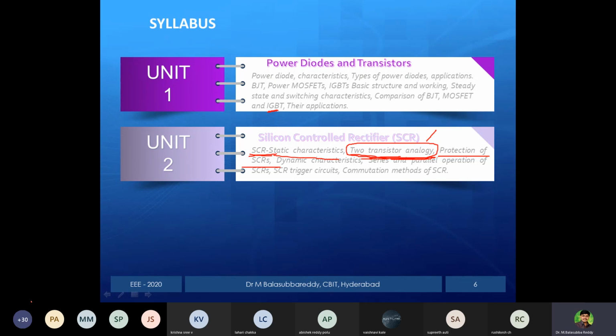This loss is converted into heat, and that heat is generated in the armature. If you do not cool it down and continuously run the machine at full load, the losses are converted into heat, and that heat will go beyond the specified withstand limit of the armature. Then there is a chance of damage to the armature. That is the reason we use water there, so it cools down and the temperature stays within the limit, like in a transformer.